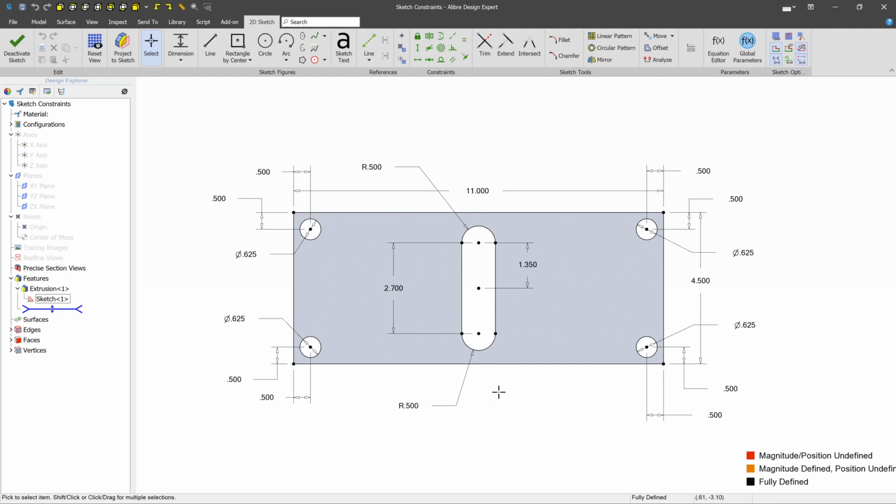But let's say you need to make a change to something, right? We want to modify the size of these holes, maybe. So we're going to type in 0.5, and now we have to go to this hole and type in 0.5, go to this hole and type in 0.5, go to this hole and type in 0.5. And as part of this change, we also need to change the offset of each of these holes. So all of a sudden, you're not only touching dozens of different things, but you might miss one. And what happens then, right? You go to production and all of a sudden one hole out of 30 is the wrong size. And now you've wasted a bunch of time and money.